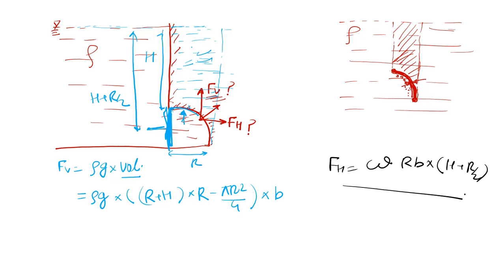So now you are able to understand, right? Even if it is in the inverse direction, what you have to do is imagine a fluid on top of the curved surface with a free surface equivalent to the previous fluid. By assuming it is on top, you calculate the vertical force and it will balance each other. That is how we understood how these things are balanced and equal. So now let us move to our next problem.